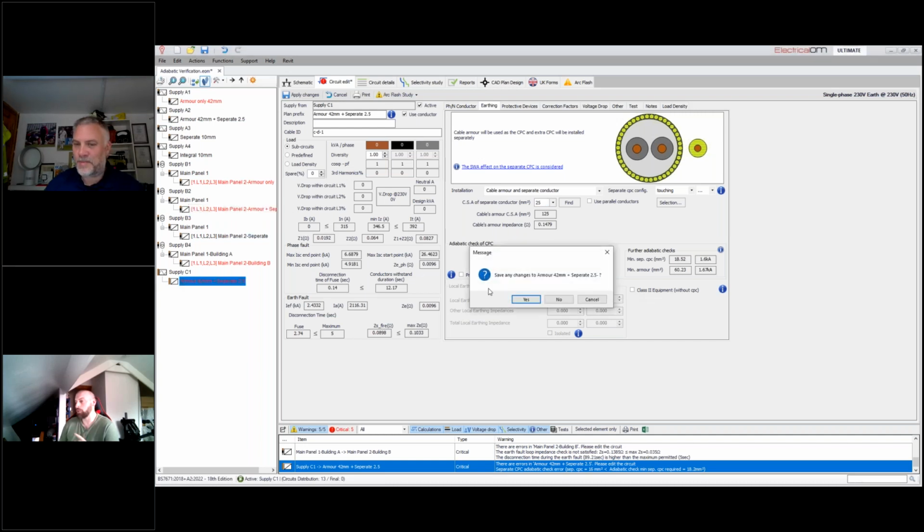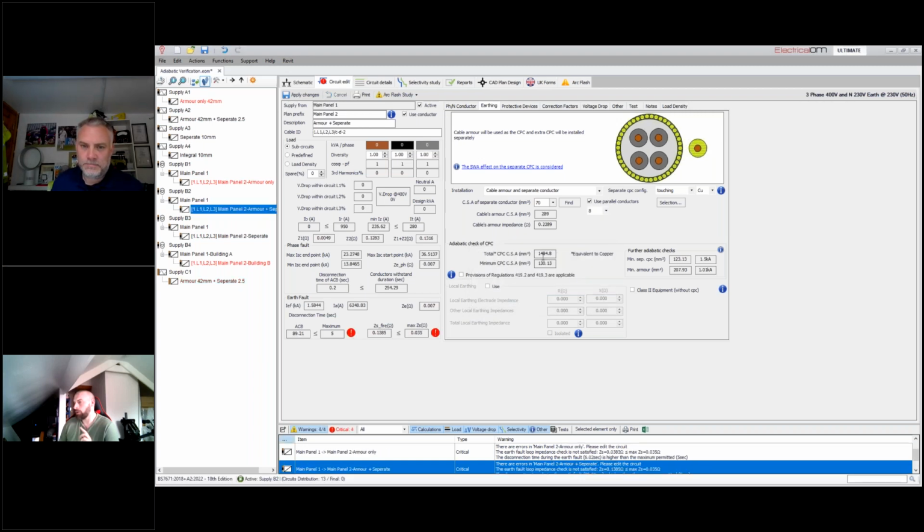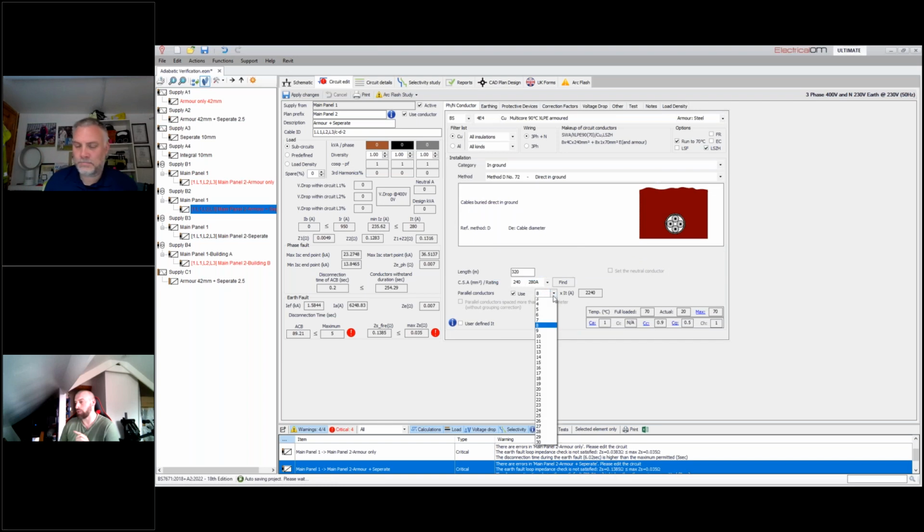In terms of this particular issue with the multi-core cable, I'm going to change to single cores and use aluminium armoreds, because I can overall use less armored cable because I don't have to take into account the parallel effects. So it's a much easier, quicker fix overall, and I'll probably get away with using fewer armoreds in parallel as well, because I increased the number of armoreds in parallel specifically because I'm trying to get so much power from A to B.